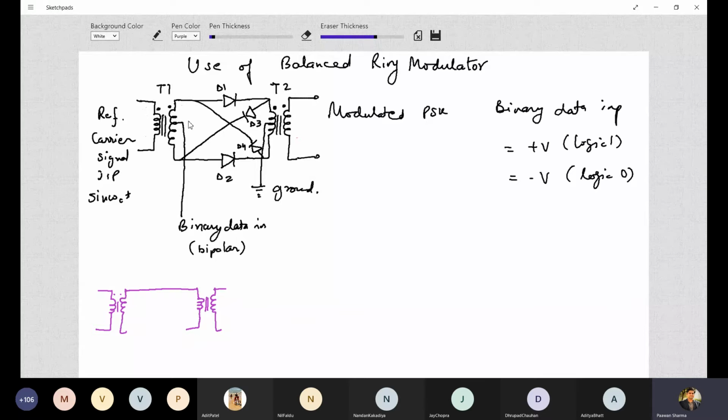It's this T2 side, this T1 transformer, T2 transformer, and this also will be connected. So this is our plus V, this is our ground, and these two dots are there. Here input is sin omega ct. Since these two dots are on the same side, same polarity signal will occur. The same polarity signal is reaching the primary coil of this transformer T2. Since these dots are also on the same side, a similar phase signal will be generated at the output of this T2 transformer.